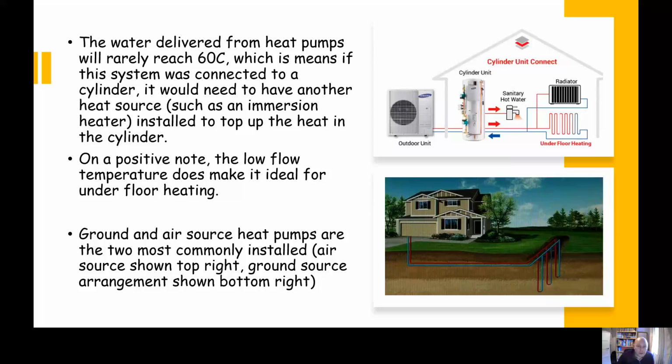Water delivered from heat pumps rarely reaches 60 degrees. I mean, that would be an extremely good day if it was up towards 60 degrees. So therefore, like I've said, if you did connect it to a cylinder, it would need another heat source, for example an immersion heater, or potentially even a gas boiler to bump that heat up, essentially.